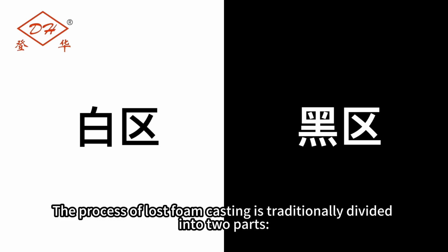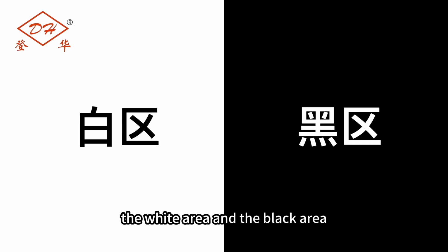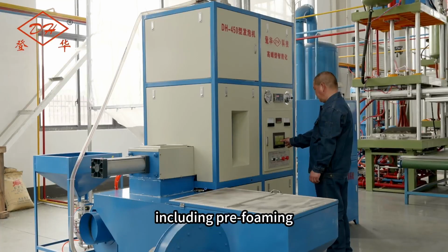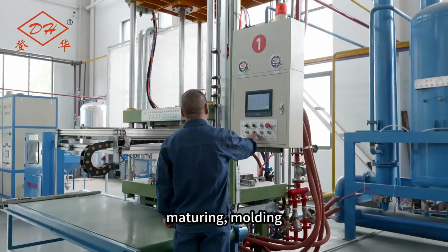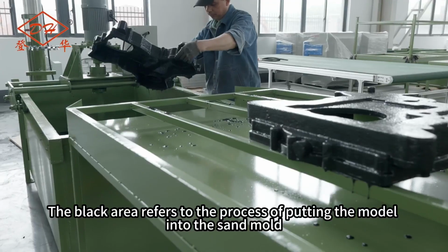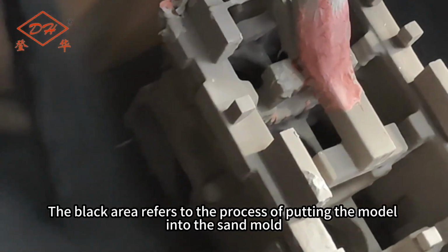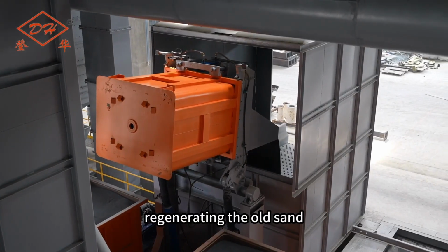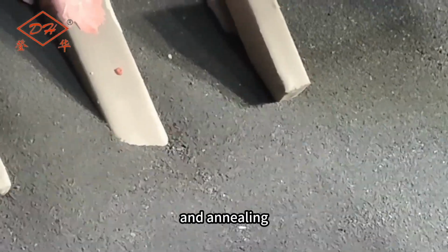The process of lost foam casting is traditionally divided into 2 parts, the white area and the black area. The white area refers to the process of making the white foam model, including pre-foaming, maturing, molding, bonding, coating, and drying. The black area refers to the process of putting the model into the sand mold, filling the sand, melting the metal, casting, regenerating the old sand, cleaning the casting, and annealing.